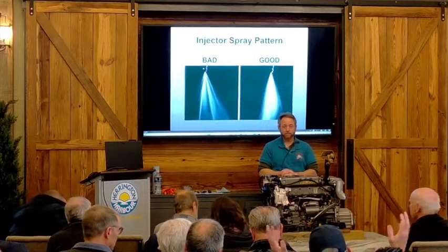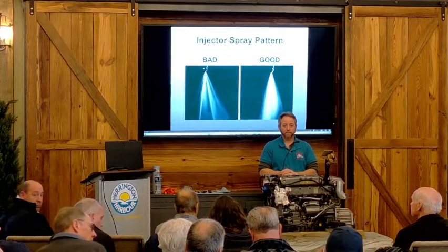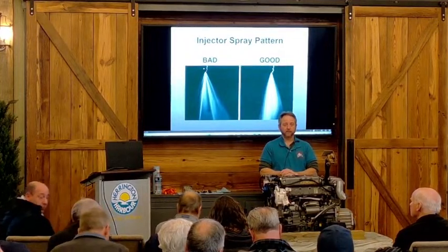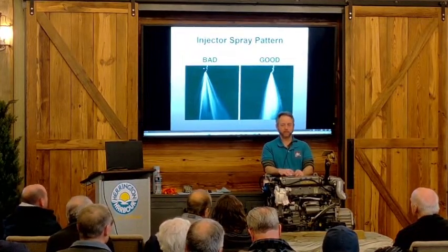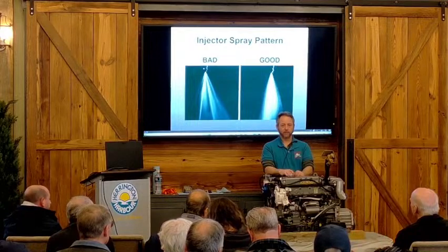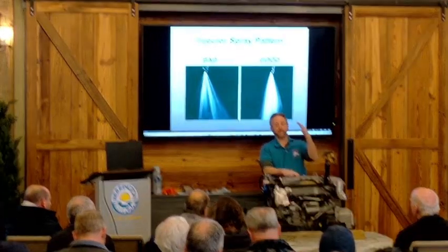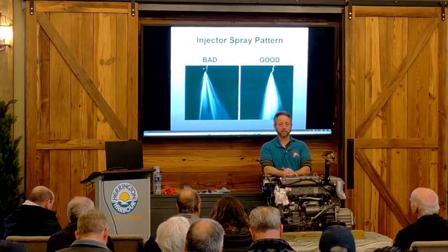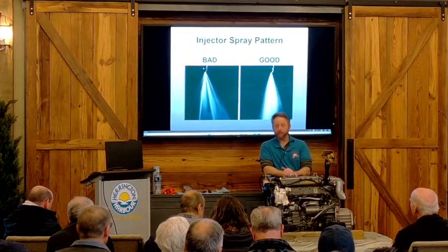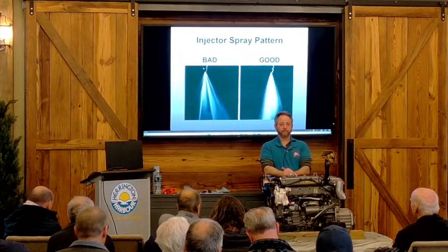If you did do that Home Depot fix with the temperature gauge, what would be a normal operating temperature? Well, we want to see temperatures under 120 degrees Fahrenheit when it's completely sealed up. If it's hotter than that without the blower running, run the blower and see if it comes within the range or below the range. What is the range? Below 120. Oh, okay. There's no lower, right? No.